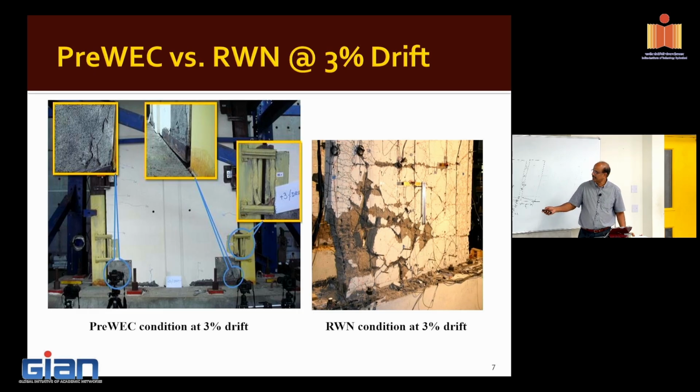Because with these cracks, every time a crack opens and closes, the debris goes inside, right? The crushed concrete. So they don't completely close, and each time they actually grow more. It's not significant, but we pushed the problem to, it's a seismic problem, it's not a precast problem, it should be looked at.